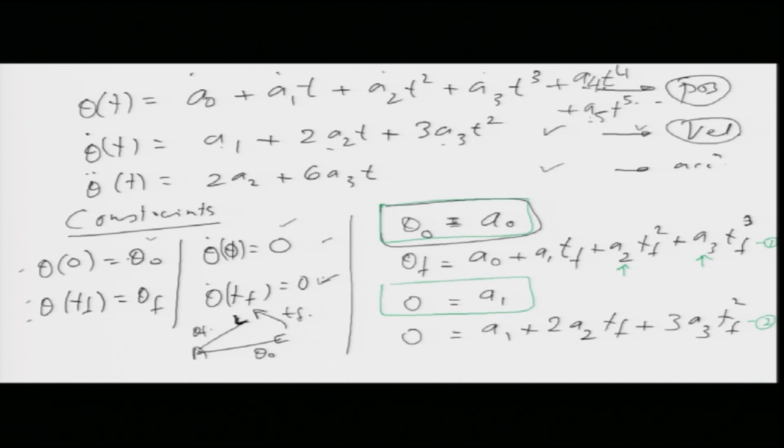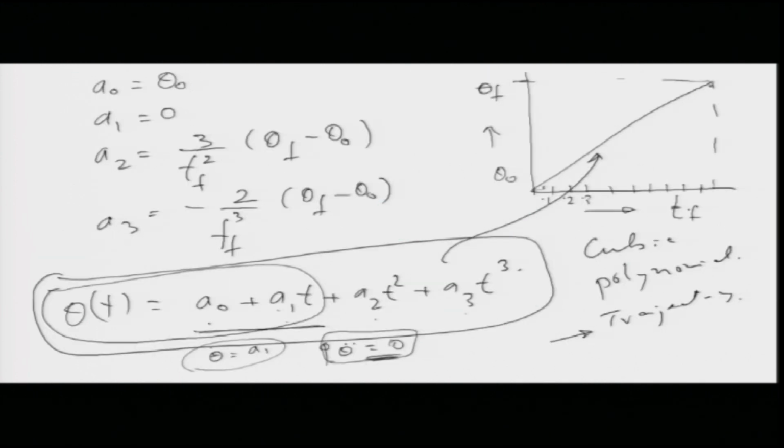Normally we use only cubic polynomials, but if you want a system where you are controlling jerk, meaning controlling accelerations, in such cases we might need a controlled acceleration, in which case I need to add 2 more terms, t^4 and t^5. But in this case we will just keep it with a cubic polynomial. So, this essentially shows that a straight line is not possible. The trajectory that we will be getting will be something like this, where the system is starting, then it is going up, the velocities are changing and then it is coming to rest.